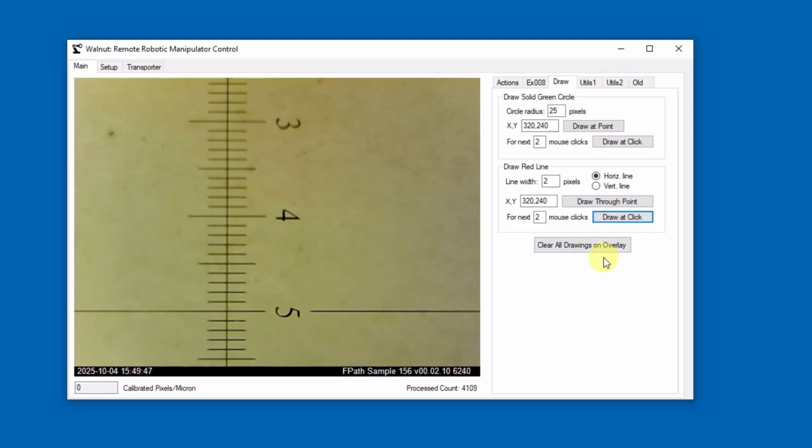We use a tool in this group to draw a line on one of the bars of the calibration slide. Let's draw it here on the large 5 millimeter marker position. The red line appears on every frame. This is why it appears fixed on the display. For those that are interested, the technique here is not to directly modify each frame by reproducing the draw command over and over again. Rather, a second transform is placed in the processing sequence. It keeps a transparent video frame in memory, and the line is actually drawn on that frame one time only. Then some much faster and highly optimized code overlays that frame onto the original image. For those that enjoy a bit of trivia, this sort of thing is called compositing. Anyways, back to the point.